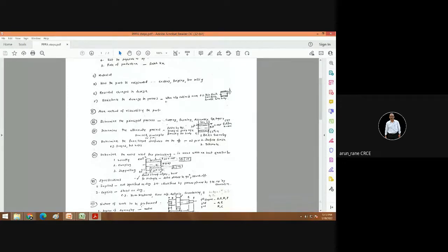Similarly here you should have knowledge of various processes, how the same component can be done by different processes, and out of these you have to select the most suitable depending upon the quantity, the material, and the product requirement, and of course well within your budget constraints. For example, you can finish the bore very well by broaching, and it will be the fastest operation. But that broach itself will cost around 1 lakh rupees. So you have to have a trade-off between the cost, quantity, tolerance; all these factors a process engineer has to consider.